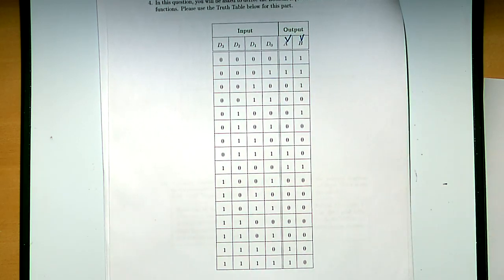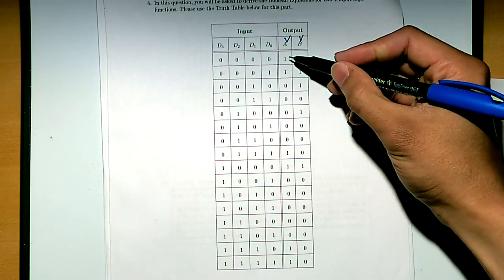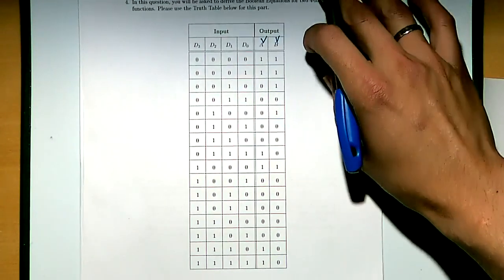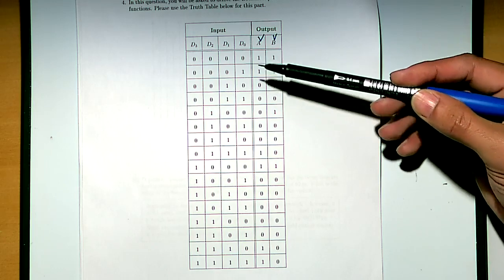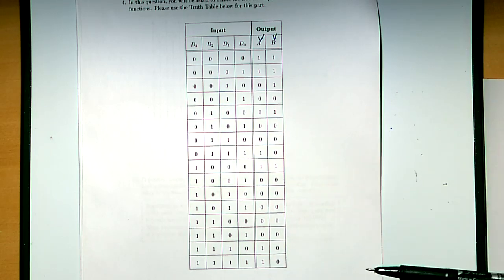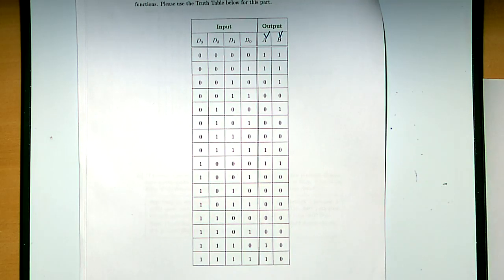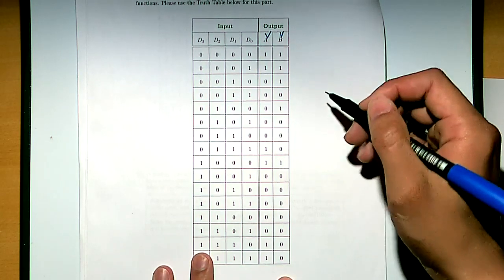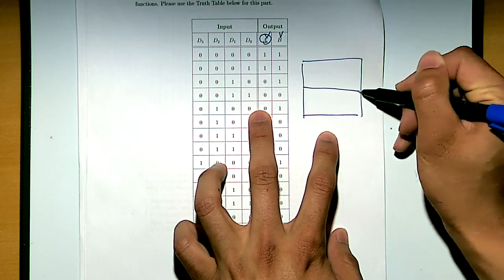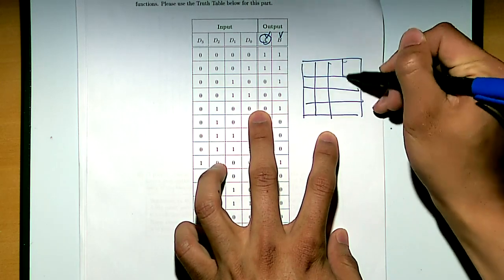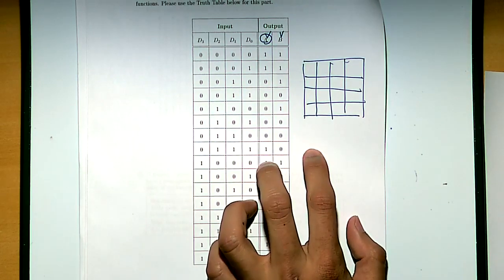So these are 2 functions, A and B. I can already give you a quick overview. The value of A is 1 when there are at least 3 consecutive 1s or 3 consecutive 0s in the input. But that is not really important. Basically, what you're given is any truth table, and we would typically ask you to derive a representation for this output A, and to minimize it to make it more compact. So for function A, I'm going to draw it over here. You can use the K-map, and transform the truth table onto this K-map.